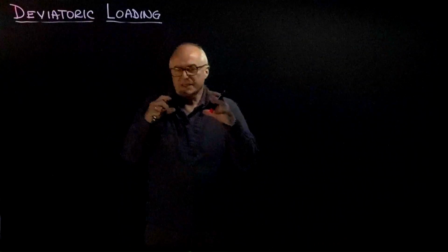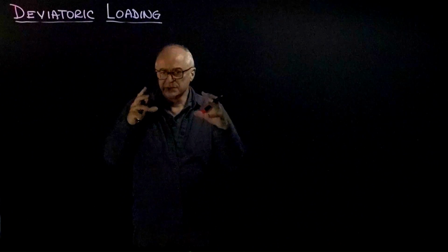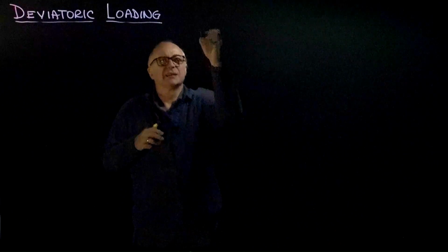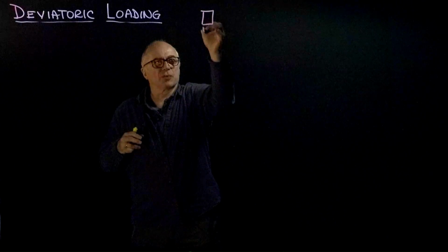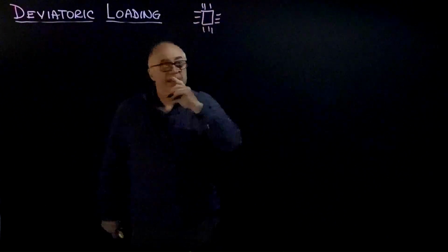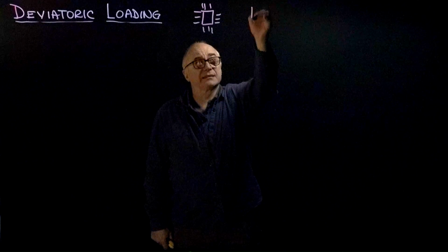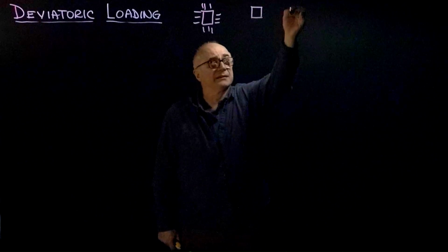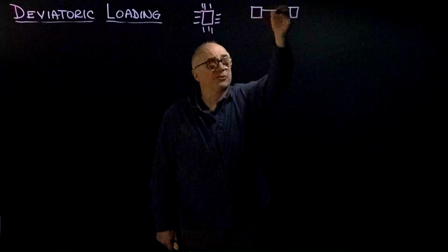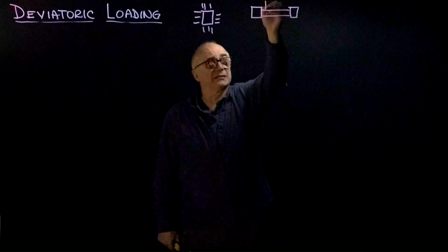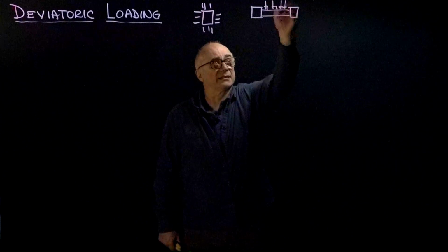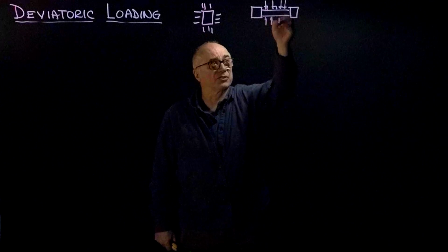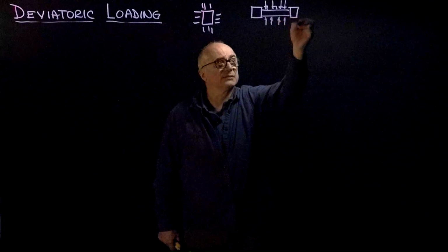Imagine that we take a soil mass inside a balloon and we squeeze it. That would be isotropic confinement. We could also place it inside a very thick ring to enforce zero lateral strain deformation, that is, epsilon horizontal equal to zero loading.